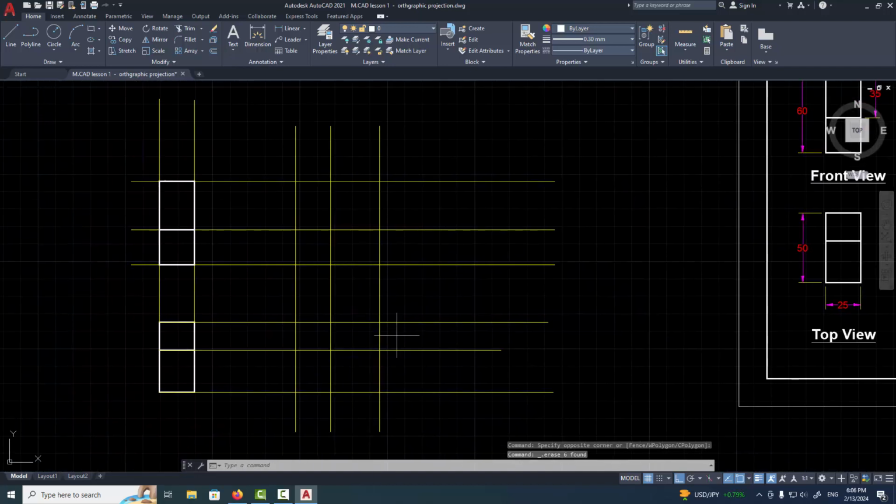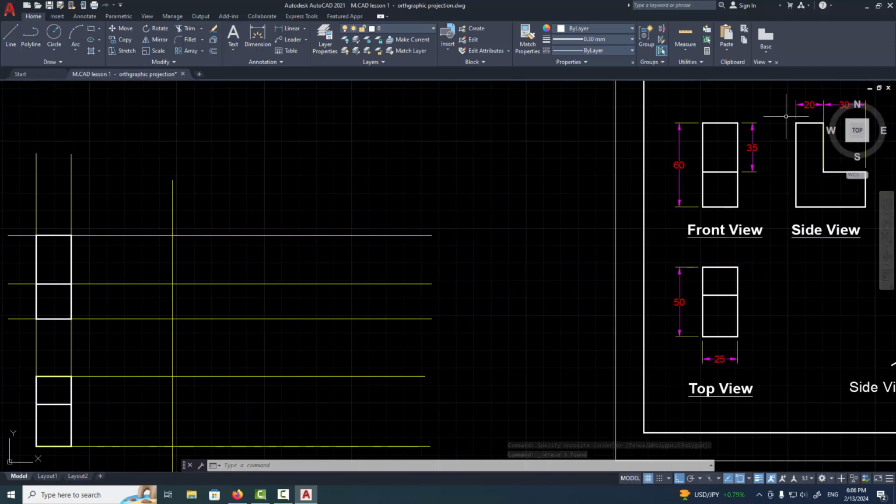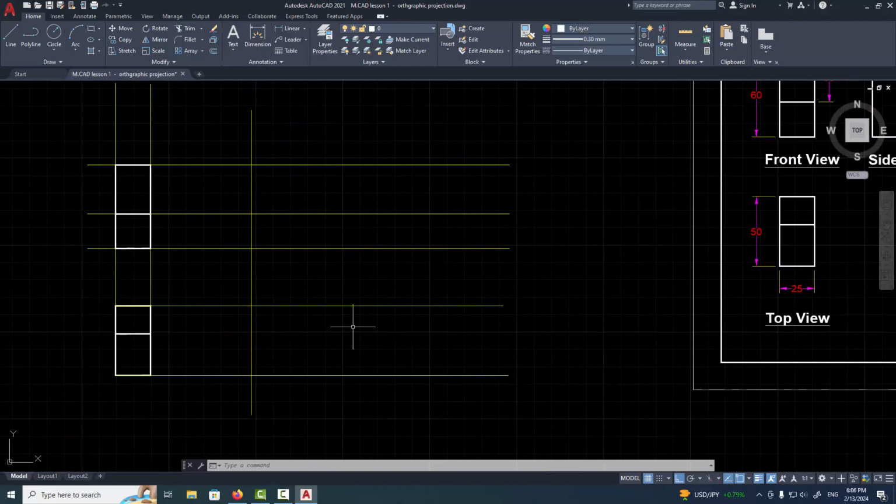We will also delete the construction lines we extended except for this vertical one, as this vertical line is this line over here. And then we need to have a diagonal line from the top point that will intersect the horizontal lines from the top end to the bottom one. Type the line command, then pick the top corner.